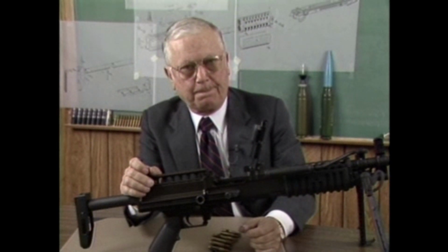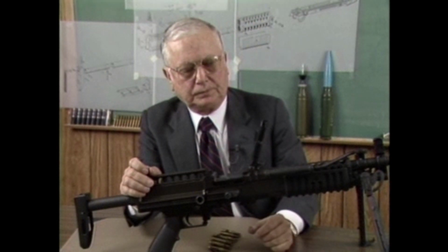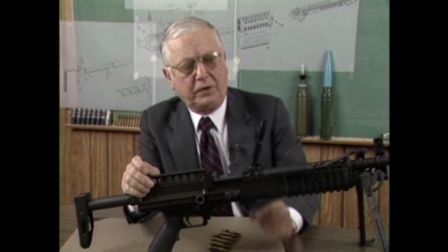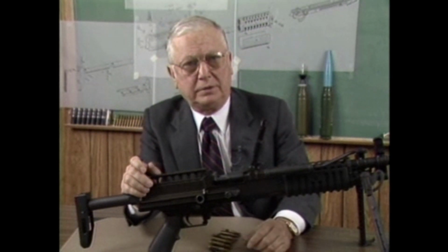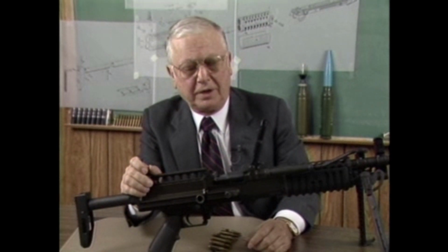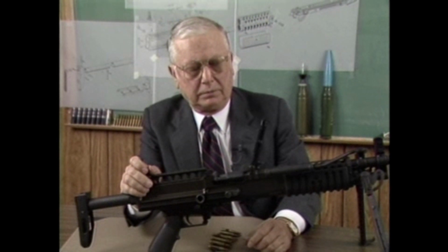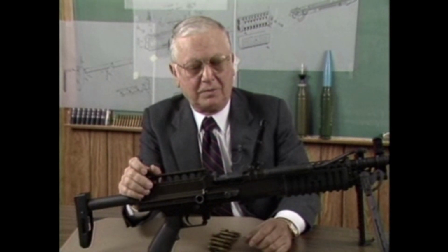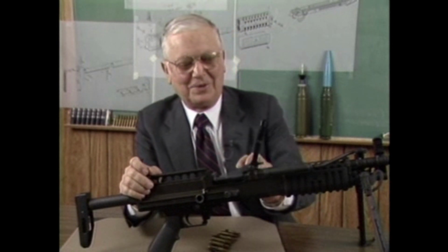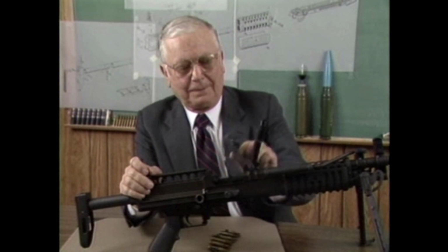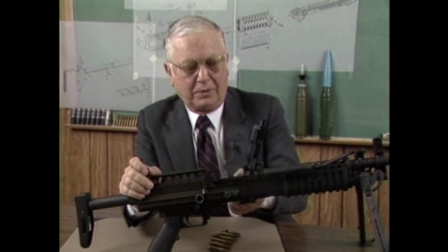How do the number of parts in that feed system compare to what exists in, say, the Stoner 63? Well, it's quite a bit simpler. In the feed cover alone, it probably has about half the parts. And in a case like the 249, it'd probably be even more favorable than that in the ratio. So that has two effects, right? It reduces cost and also eliminates things that can go wrong. Well, that's right. Anytime you can simplify it and reduce the number of parts, you usually reduce the number of things that go wrong. Not all the time, but this feed system too, the way it works, has one other function.